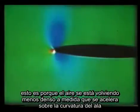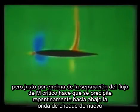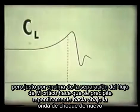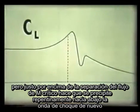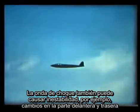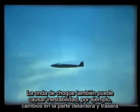This is because the air is becoming less dense as it speeds up over the curvature of the wing. But just above M crit, flow separation makes it plunge suddenly downwards. Later on, it increases slightly, then falls again. The shock stall can also cause instability. For instance, changes in fore and aft trim.